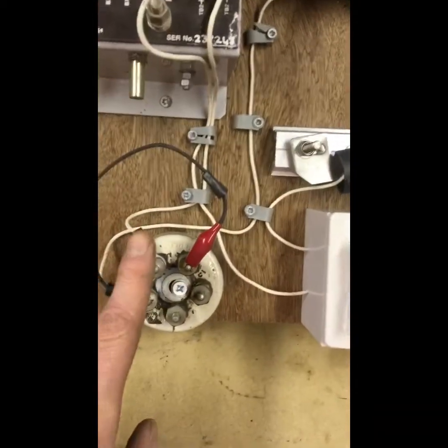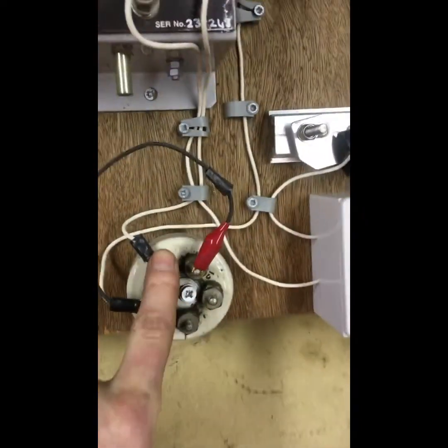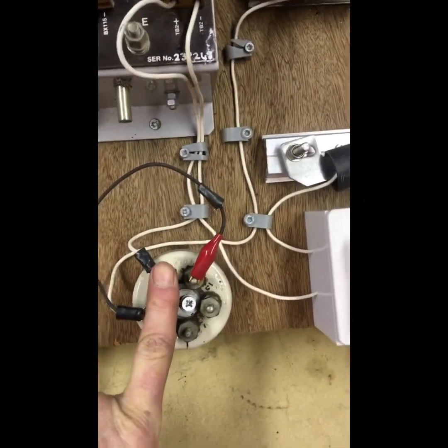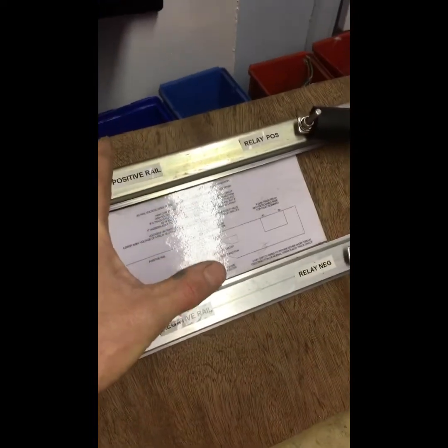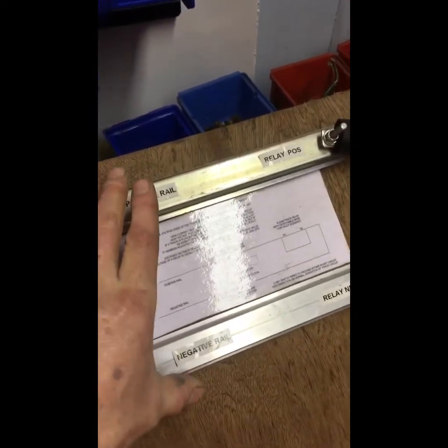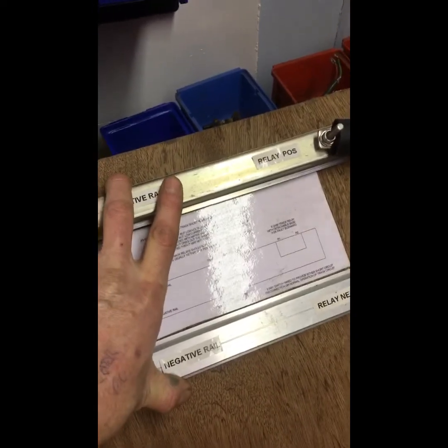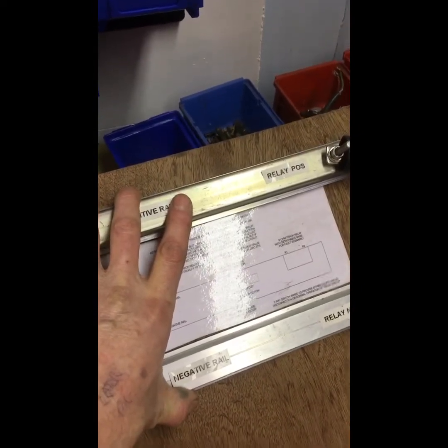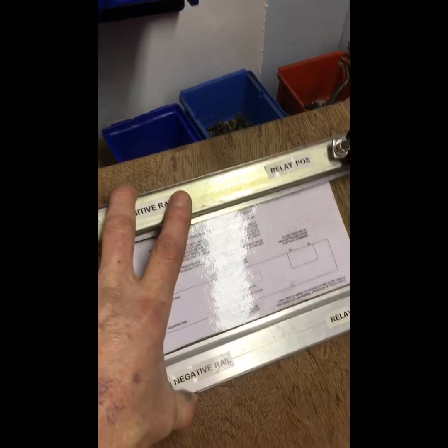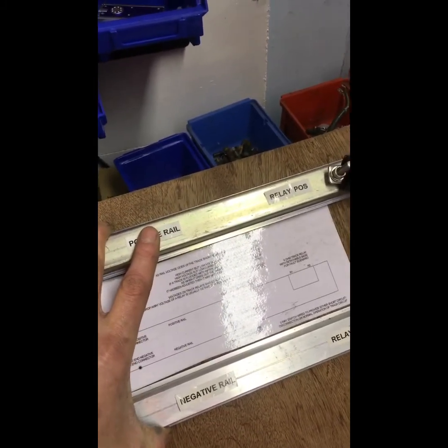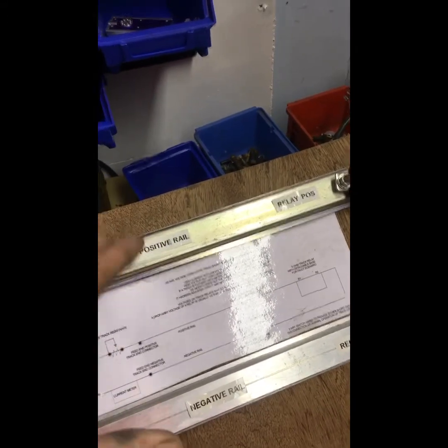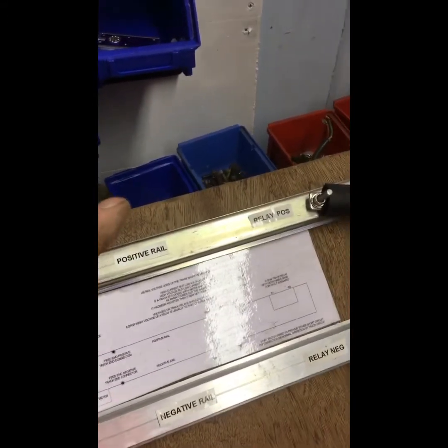Also, the resistor is used for setting up the shunt values, because as you can appreciate, the differences in resistance between the rails depends on the sleepers, the condition of the ballast, and how impregnated the ballast is with things like mud and ash. A lot of locomotive ash can cause a lot of problems in track circuits. You can short it out because it is an acidic means.